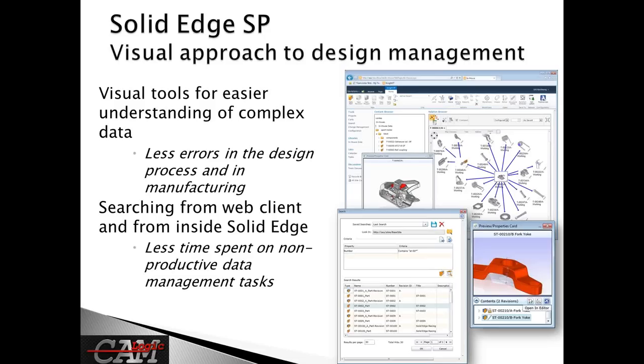So you can get in there, and through the relation browser, you can take a look at, all right, I found my project, I found what I need to look for. And then in the relation browser, you can see that it almost maps out: okay, this is the assembly, these are all the components in that assembly, here's a sub-assembly that's in that assembly, and here's all the components in that sub-assembly. So it's really good at laying that out and showing that to you.